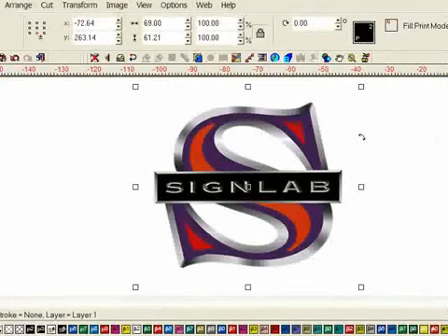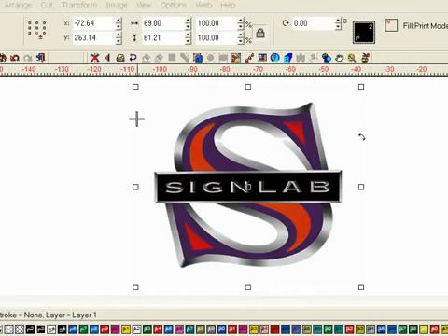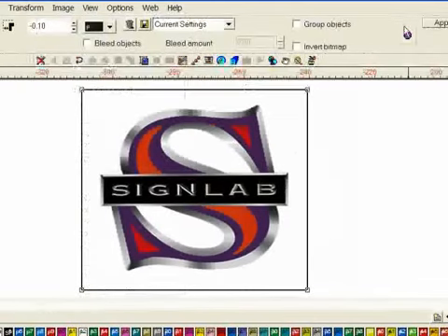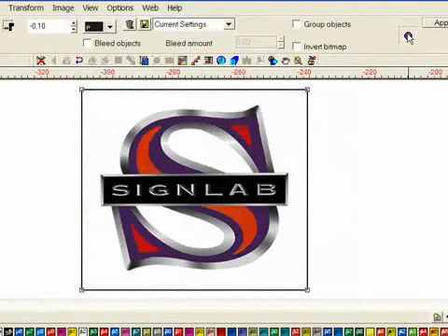First, a couple of tips on applying contour and half-cut paths to bitmap objects. Take a look at this logo. Unlike the previous example, it does not have a clipped path, and you can see a white box around it when it's moved over a dark background. When applying a contour line to this object, I would need to select this option, Cut Inside Bitmaps, so that my contour line will do just that and form a tight path around the logo.